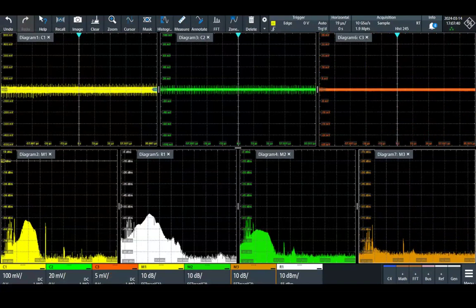So something that you will do probably is to try to identify who is creating this energy. Remember, this is not harmonics of your signal. I am not switching at 100 megahertz. They are not harmonics of my 500 kilohertz switching frequency in the DC-DC converter. Perhaps it's an oscillation, perhaps it's a ringing or resonance, no?